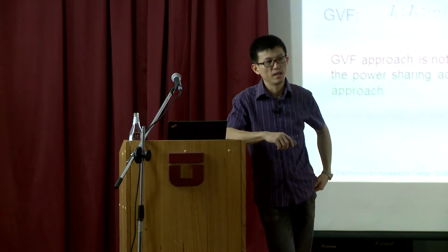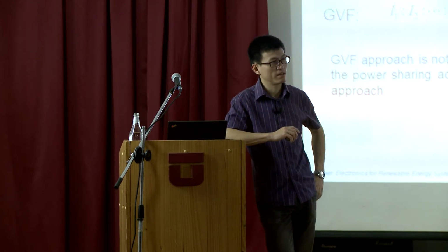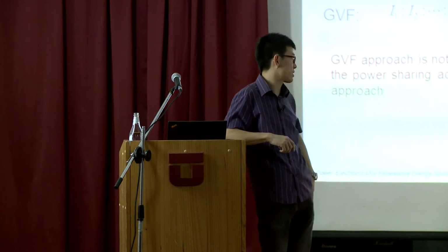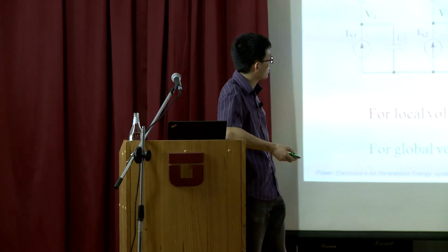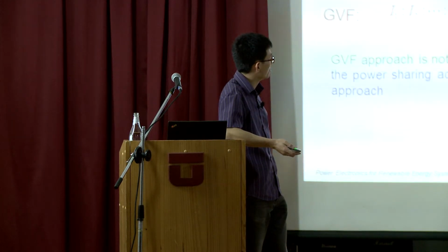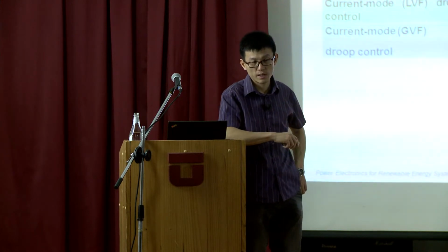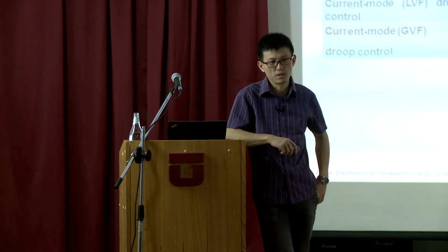But between local voltage feedback and global voltage feedback, there's no impact. Again, it's a compromise here. What you gain is just accurate power sharing, but for stability issues, you have no gain at all.